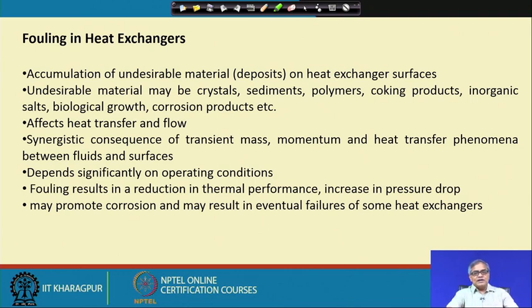But then when the heat exchanger is operated over some time, the fouling starts taking place, and fouling is a progressive phenomenon. That means, with time the fouling increases, or the deposit on the surface increases. So, obviously, there will be some change, good or bad, we will see later on, in the performance of the heat exchanger. If we are unaware and do not give some consideration to the fouling, then our heat exchanger will not perform properly.